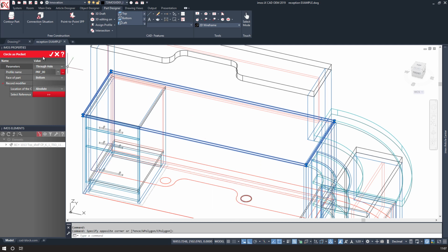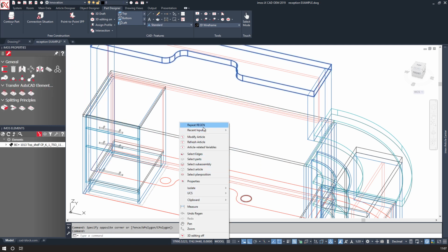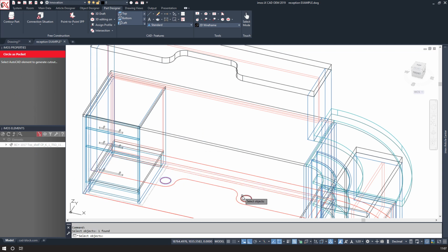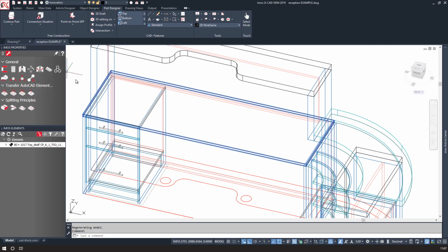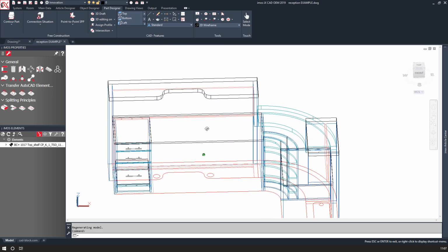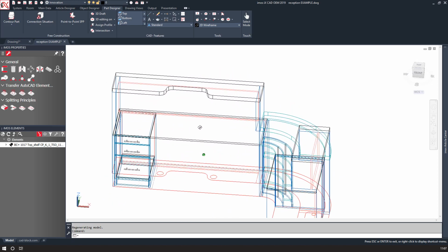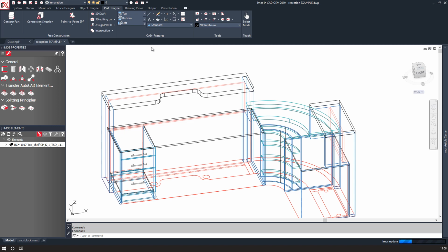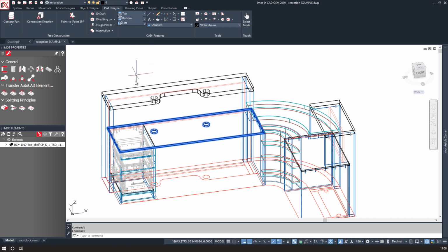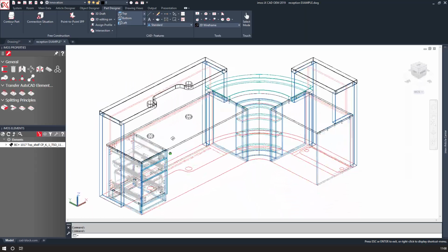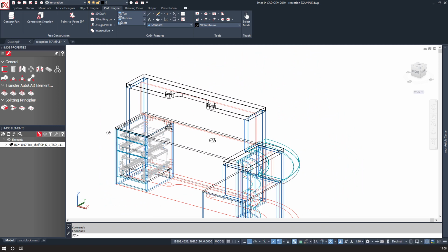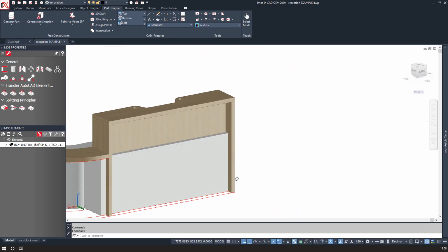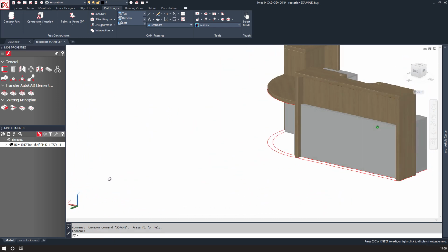And because imos can detect the different parts and material and machining features, it will know which machining elements to use certain tools on. It will know that certain thicknesses of machined parts need to have certain tools or feed, speeds, lead in, lead out. All of these elements are based on conditional logic, so it will then automatically create all of the machining data with all of the tooling information automatically assigned. So here you can see, after I've turned the level of information all the way up to the highest level, the pockets have been passed into all of the parts and are now ready for the next step, which will be documentation.